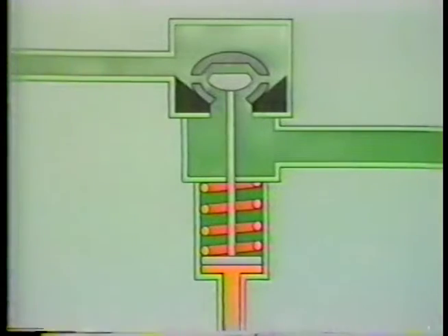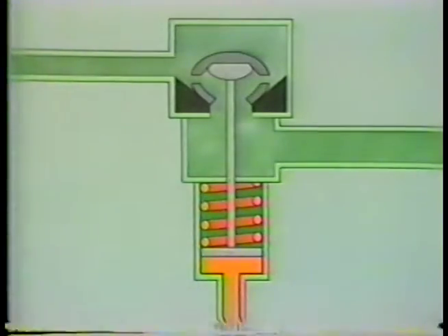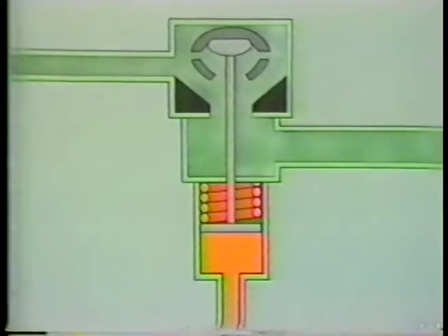This arrangement provides a fine control of steam flow, enabling the speed of the turbine to be increased gradually during startup. When the turbine is up to speed, the bypass valve disc is raised more, lifting the main stop valve disc off its seat. In addition, the other main stop valves are also open. In this position, there is a full flow of steam towards the turbine.